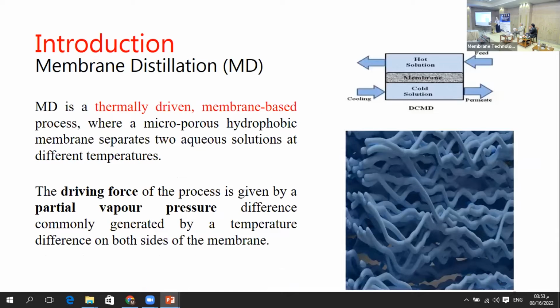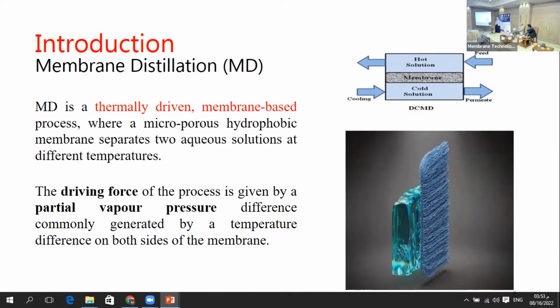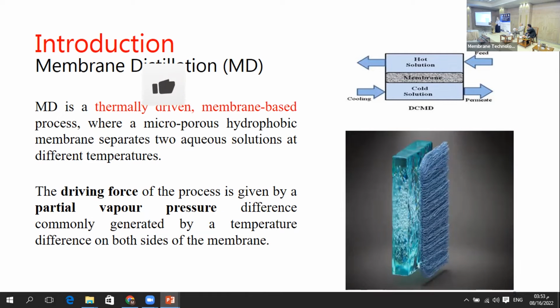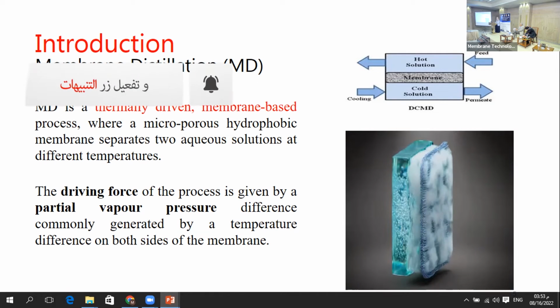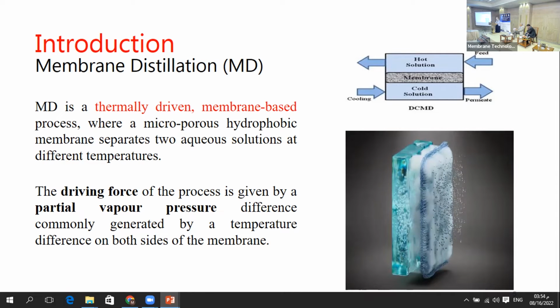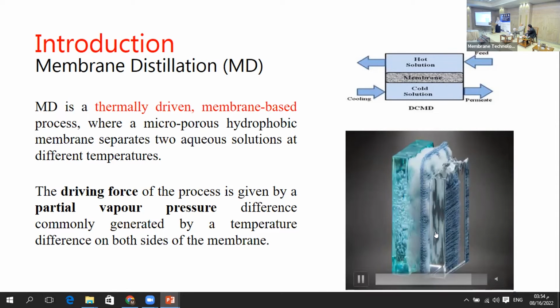So what is membrane distillation? Membrane distillation is a thermally driven membrane-based technique where a microporous membrane separates two aqueous solutions at different temperatures. The driving force for the process is the partial vapor pressure difference on both sides of the membrane, which is originally generated by a temperature difference on both sides of the membrane. This video illustrates the operation of the MD process.